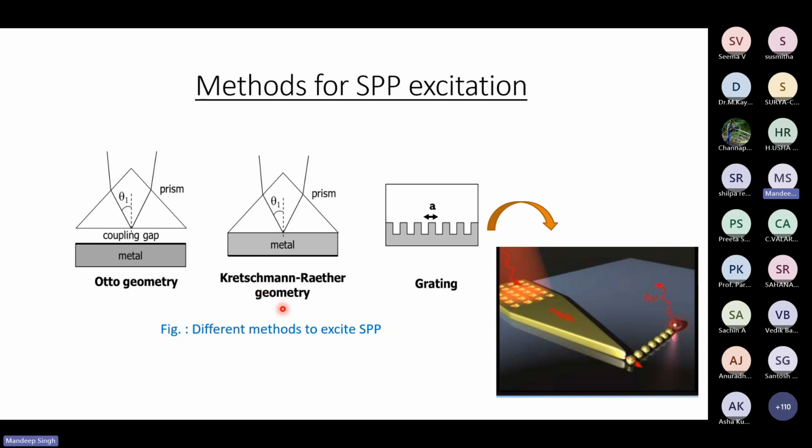For nanophotonic sensors, we have to follow some different methods that are available. Let's start from the first method proposed by the scientists for simple SPR sensors. They have taken a very thin film metal layer, and above that they have deposited a very thin dielectric layer, the black color line. They are using a prism, because for exciting any surface plasmon you have to shine the light at a particular angle, like here they are using the theta 1 angle. To maintain such an angle, we have to use a prism.